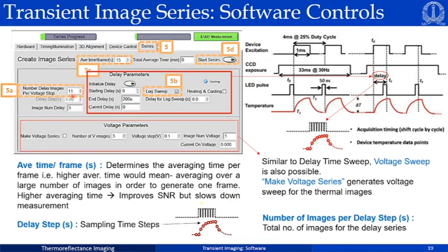The next parameter of interest is delay step. Delay step is this delta t value. If you look at the right hand side, the delay parameters, like what would be the starting sample that you would want to measure, and in the subsequent frames how would these temperature samples shift with time. For example, you would measure at t equals minus 25, then t equals 0, then plus 25 nanoseconds, then plus 50, plus 75, plus 100, plus 150, like that you cover the whole excitation pulse width. So this number will be typed in here.